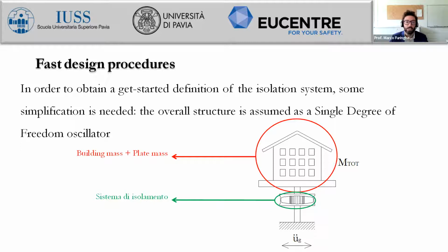It was approximately equal to the stiffness coefficient of the isolation system, simply because we expect the stiffness of the building to be much higher than the stiffness associated with the isolation system, because we needed to provide the proper period shift.